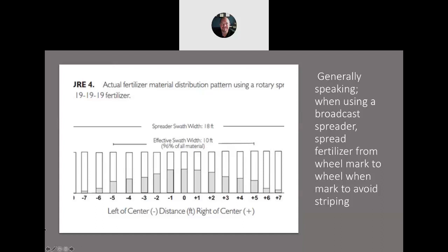When you're doing the spray though, you have to take into consideration that you have that spray width. So you want to determine your spacing based on your effective spray width first, because that is very precise and accurate. If you overlap, you can get burns. If you don't have enough overlap, you can get skips or misses in between.